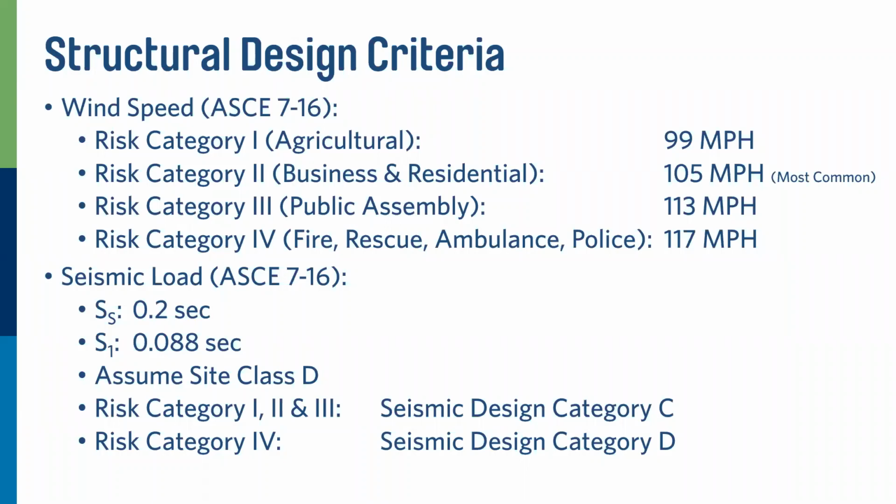We're not designing for a tornado because our tornadoes double that wind speed. We can't design for it. We're not going to make people design for it. It's uneconomical. But we do have hurricanes that come through. We border Florida, and we've had hurricanes come straight through Atlanta. And we have those winds of 75, 85, 90 mile an hour. And that's what we're designing for.